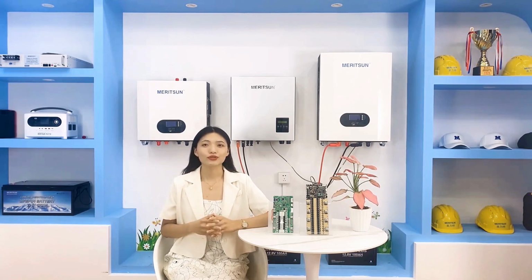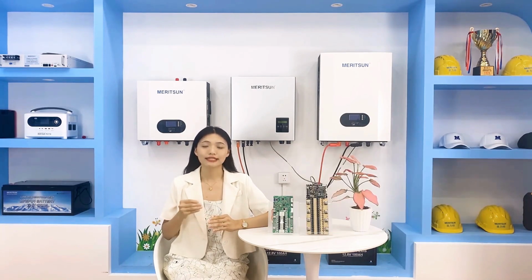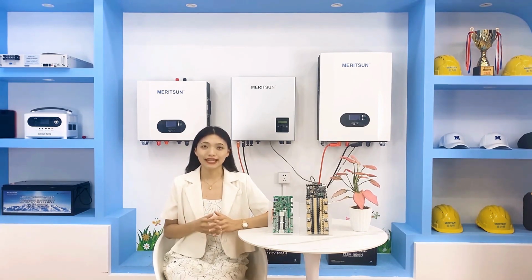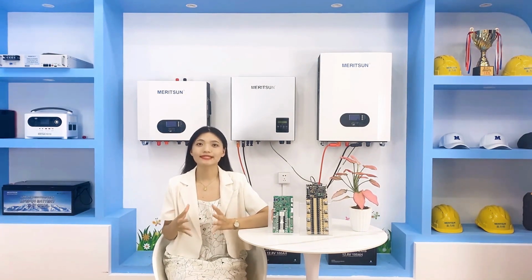Based on this, you can also understand that the ID cannot be repeated, which is the same as the dial. The logic of the dial follows the law of binary, which means for 4 dial codes, it will have 16 dial numbers for you to choose from. Usually, you can ask your suppliers for guidance on dialing the codes, or you can search the binary law on the internet and follow that. The main thing is that you should pay attention to never repeat a dial.